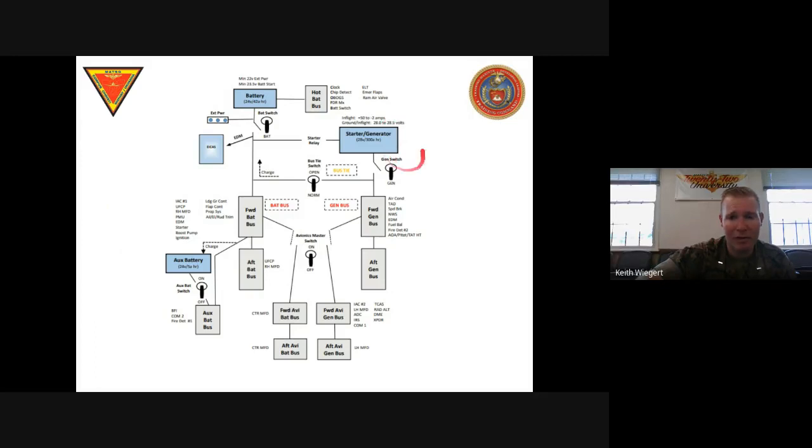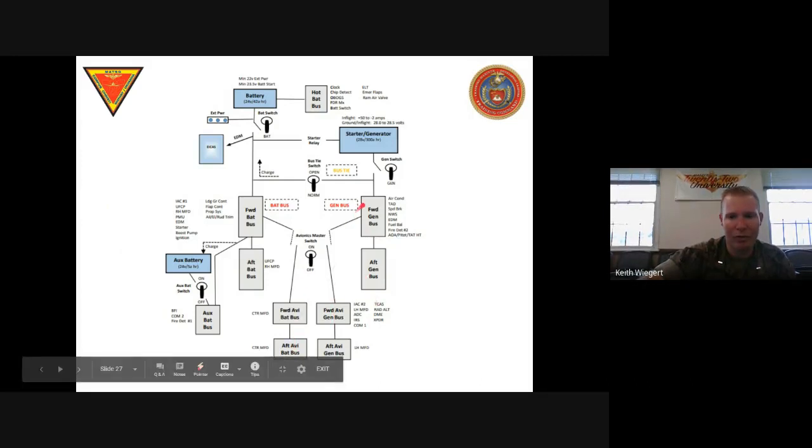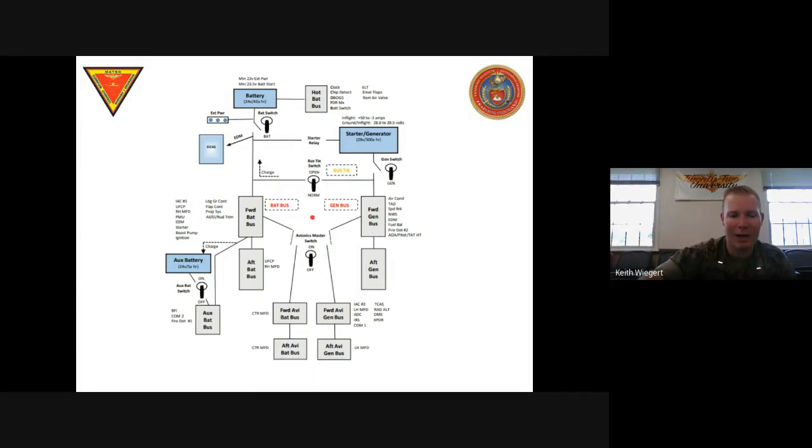Well, between turning on the generator switch and turning on the avionics master switch, I'm going to go to the next couple steps in the checklist, right? It's like 4 steps afterwards, and then you get to avionics master switch. 10 seconds need to have passed before I can turn this on. That way, it doesn't overload the electrical system, right? When I turn all of this stuff on at the same time, right? If I were to go straight to generator switch and avionics master switch at the same time, then we would risk some of these components not coming on at the appropriate time. So make sure 10 seconds has passed between turning on the generator switch and turning on the avionics master switch.